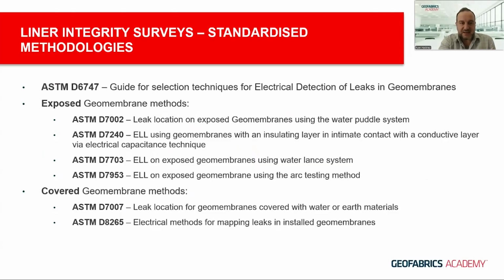So you have a guide, ASTM D6747, and that's a general guidance that will allow you to select the most appropriate methodology for conducting the survey. And we can split that into two different types of methods. So we can do surveys on geomembranes that are exposed, and there are 4 methods there. And there are methods for the situation once the geomembrane has actually been covered. So that may be with water or with earth.